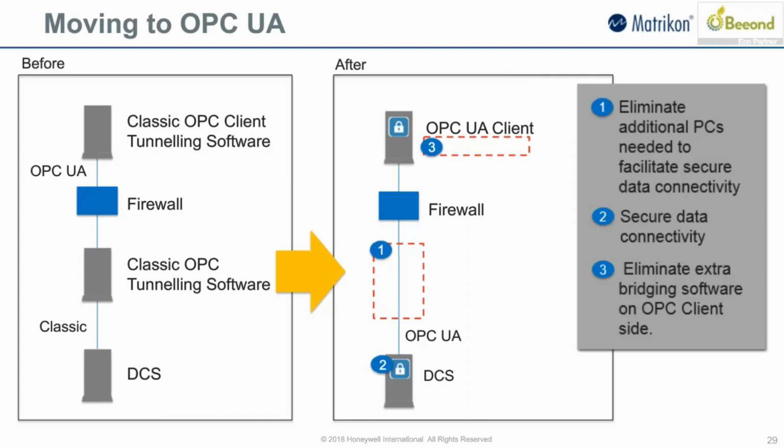They have their own OPC UA gateway that will connect locally at the plant and up through their cloud infrastructure. So OPC UA is again an enabler, allowing you to define a very different infrastructure, reducing the costs of all those expensive servers and maintenance that many end users have sitting in their factories.